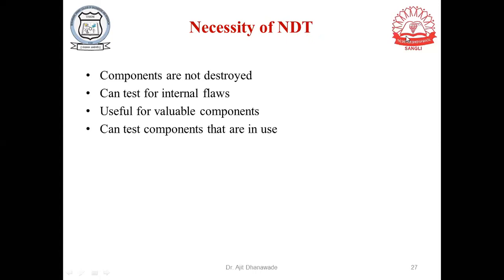Before that, we need to understand what is the necessity of non-destructive testing. See, in many applications you are not allowed to destruct the component. In some cases, the value or cost of that particular component is very high. For example, suppose a particular component of an expensive car is priced at around 50,000 or 1 lakh rupees. You cannot destruct that 1 lakh rupees component just for testing. So you need to use such a test which will not make any damage to the component, so that the component will remain as it is even after the test. You will be able to test whether there is any defect, whether there is any flaw in that particular component. So this is the first advantage of non-destructive testing.